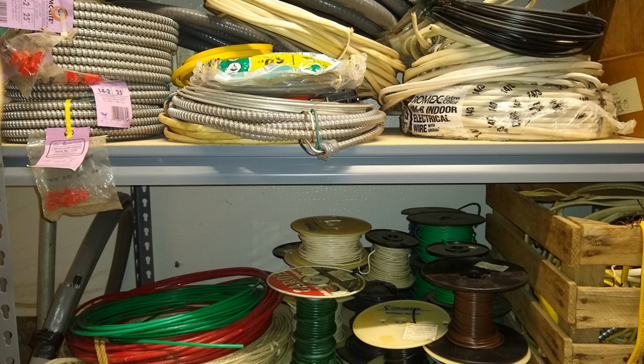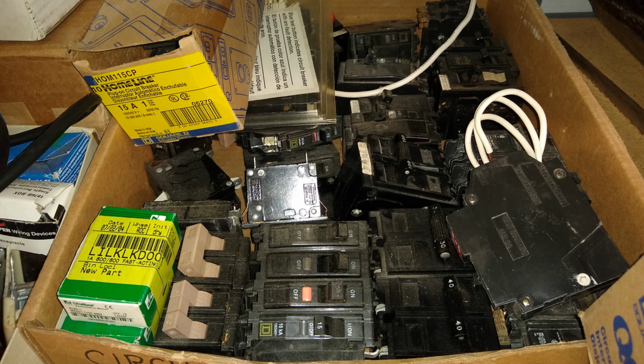After you've done all the calculations you normally need to do to size a circuit and select the conductors and overcurrent protection device, good system design should compel you to consider voltage drop, and the NEC promotes doing that.